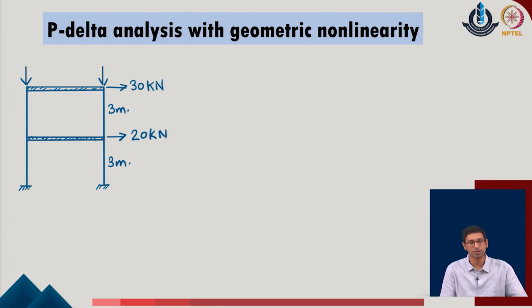Now, I am going with the procedure in a manner such that the overall approach can be extended to the same stiffness method which we did earlier. So, as a first step of analysis, we need the stiffness matrix K of the given system, or I will say the linear stiffness of the given system. I need to define the linear stiffness of the given system.